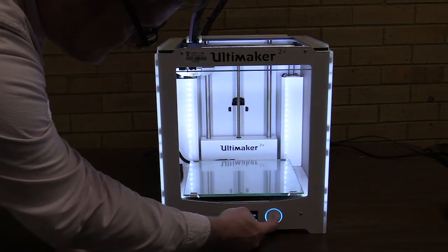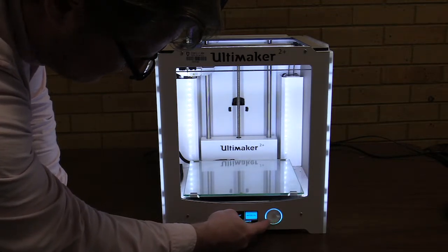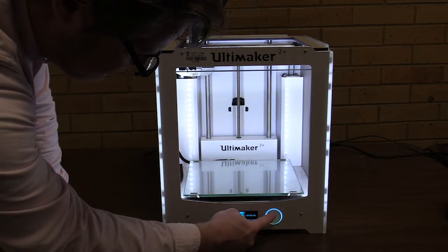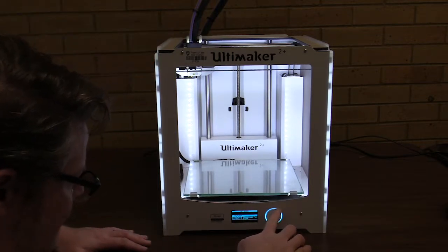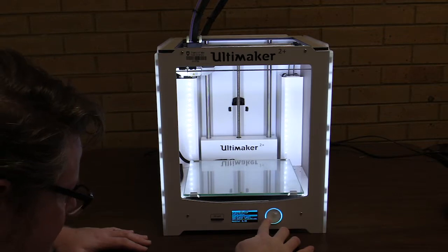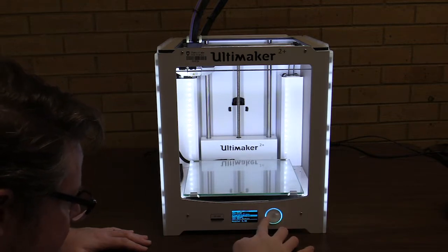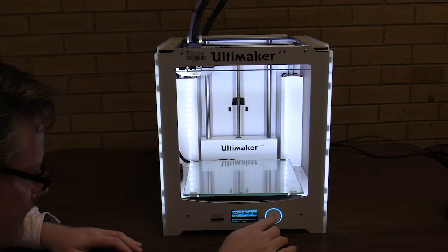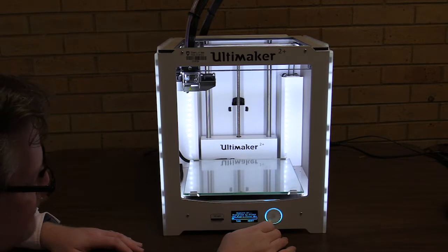Next, we're going to use this jog wheel, and we can notice that we have three different choices: print, material, and maintenance. Okay, we want to highlight print. Okay, and then I'm just going to hit the center of the jog wheel. Okay, and instead it was reading the SD card. Now we're going to have a list of all the files that are on there. And I'm looking for UM2 with my name on it. Scrolling through these, I'm not sure if they're in any sort of order, but of course last on the list is Ryan's first object, and then I will just hit the center of the wheel when I'm highlighting my file, and the printer will start.